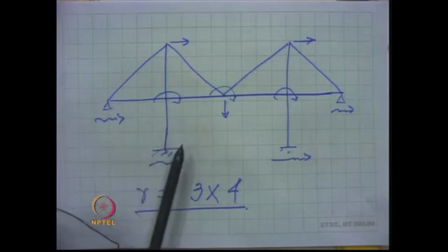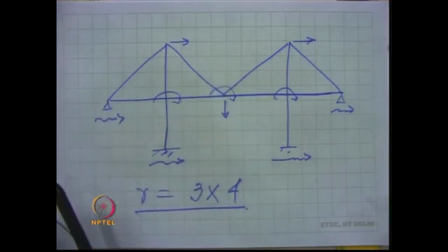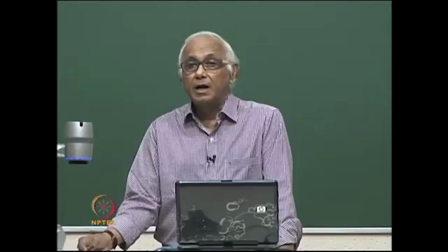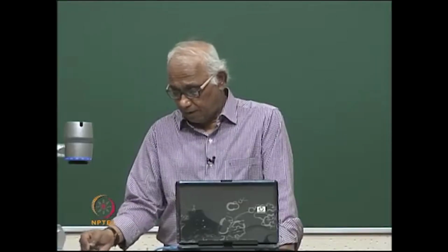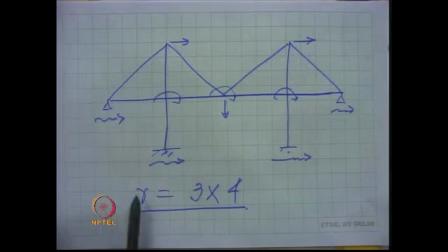Out of that, we again partitioned the stiffness matrix so that the 3 non-support degrees of freedom are identified, and from there we obtained the R matrix, that is, the influence coefficient matrix we described before.